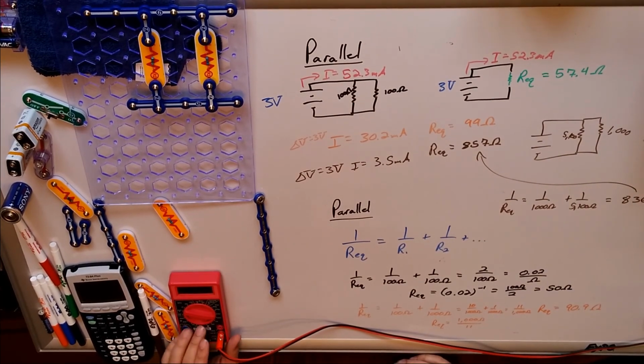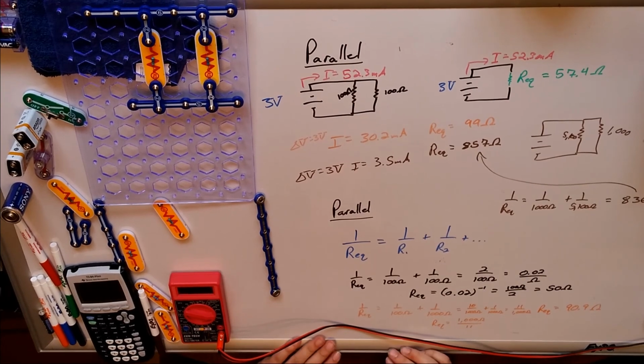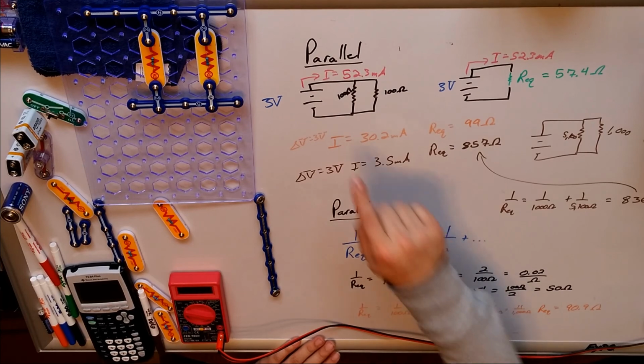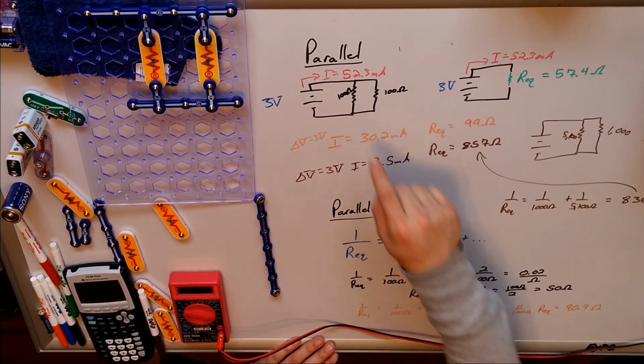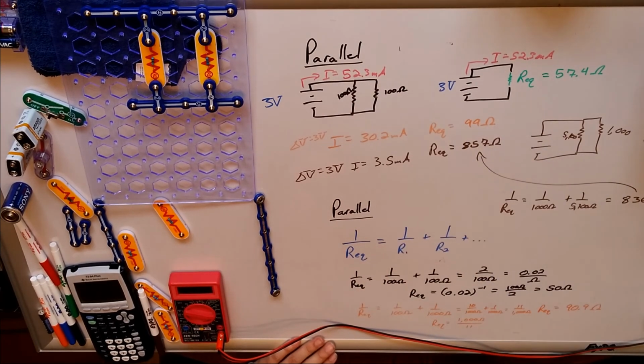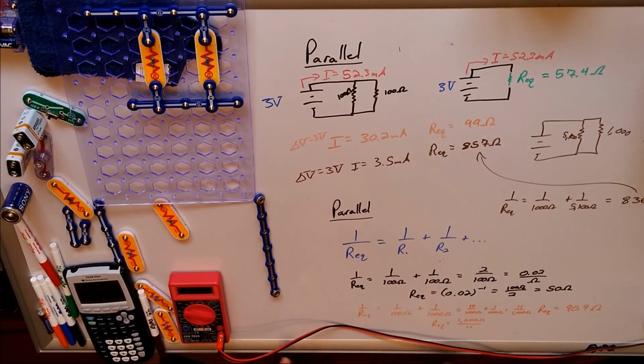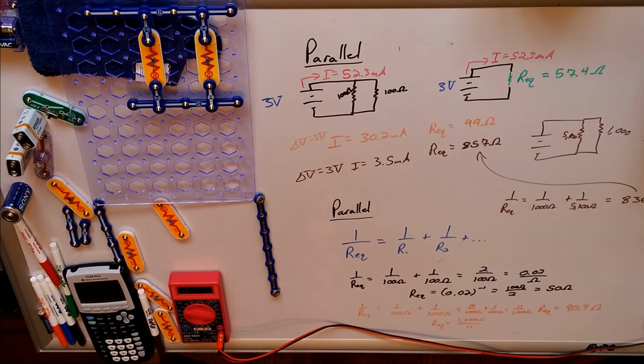When you have resistors in parallel, their equivalent resistance will always, always, always be less than any of the individual resistors. You will always end up with a number that is smaller than the smallest resistor that you have in that equivalent or in that parallel branch. When we start talking about how to interpret this in the advanced part of circuits, that'll become more clear as to why.